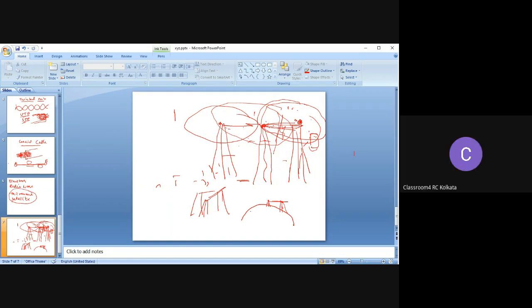So microwave travels in straight lines, and so the transmitter and receiver stations should be aligned with each other. Microwave propagation is line of sight propagation. So the towers hosting the stations should be placed so that the curvature of the earth, I already mentioned the earth is curved in nature, or any other obstacle does not interfere with the communication.